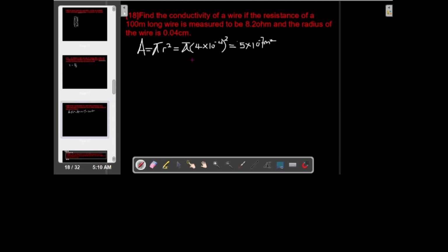That's the area. All right, so since we've cleared that, let's try to calculate our conductivity. Please, let us follow a flowchart to that formula for conductivity. I don't just want to give you the formula, I want to show you how to get it. So let's start with resistance. Resistance, as we said earlier, is what? Rho L over A. Now, what is rho again? Rho is the resistivity. So if you make rho subject of the formula, you're going to have rho is equal to R A over L. Now, there's a particular thing which is the reciprocal of this resistivity. That is 1 over resistivity. That thing is called the conductivity. So please note, conductivity is the reciprocal of resistivity.